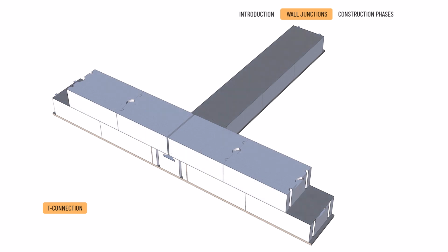In our main wall, 2 cut elements will be symmetrically placed upon the adjoining whole block, placing the joint on the center line of the joining wall. The length of the cut elements is 56.5 centimeters, leaving a vertical joint of 1 centimeter that we fill with mortar.